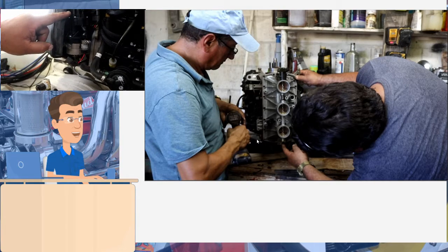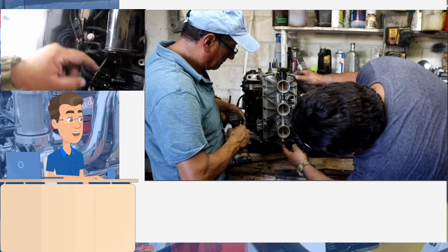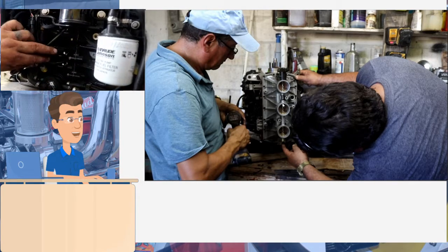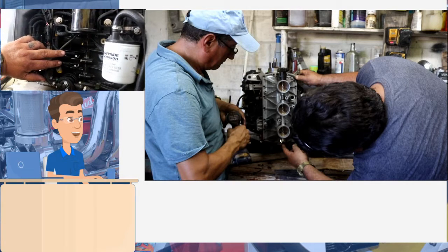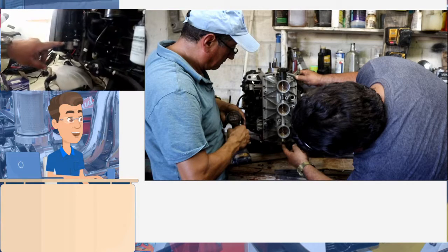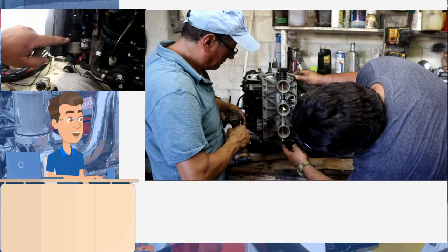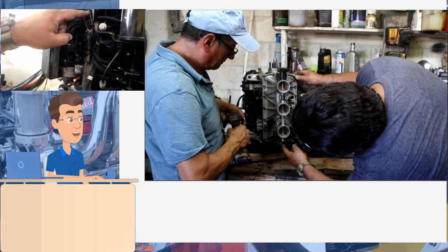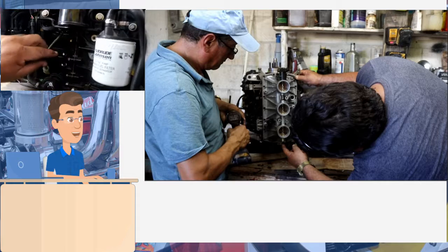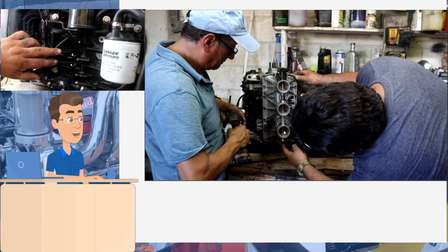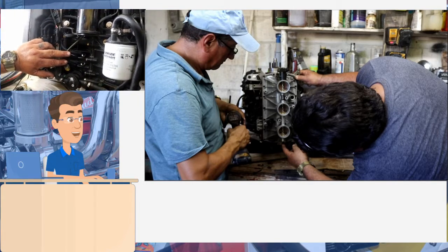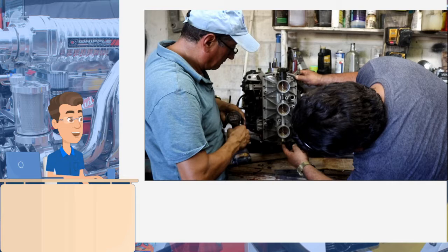The oil pump suctions the oil for two-strokes from a separate reservoir. In other words, when we remove this manifold, we have the oil and air mixed. The fuel enters directly in the combustion chamber because this engine is direct fuel injection and the injectors are located on top, on the head, and the head is on the opposite side.